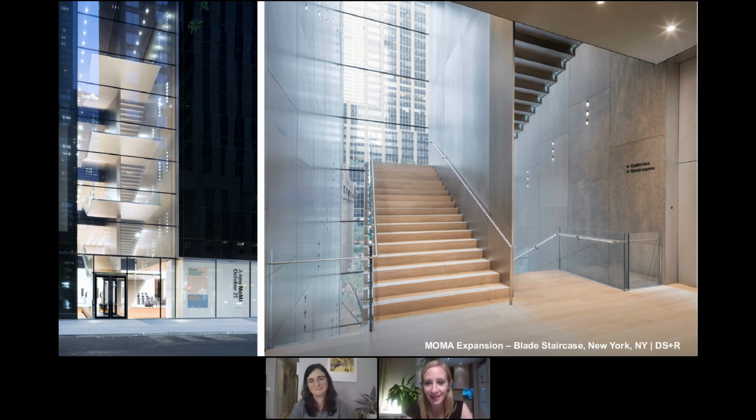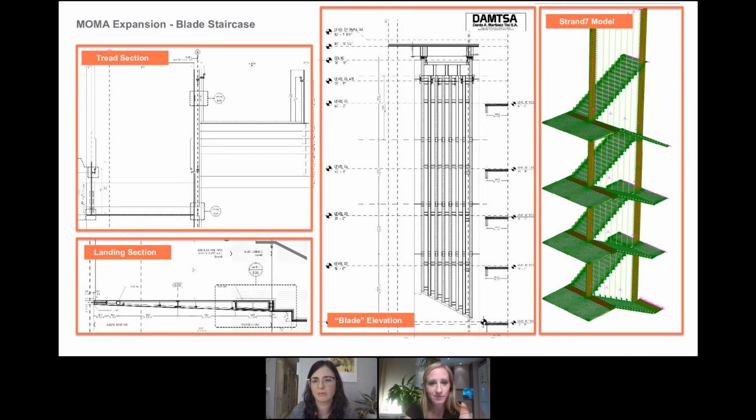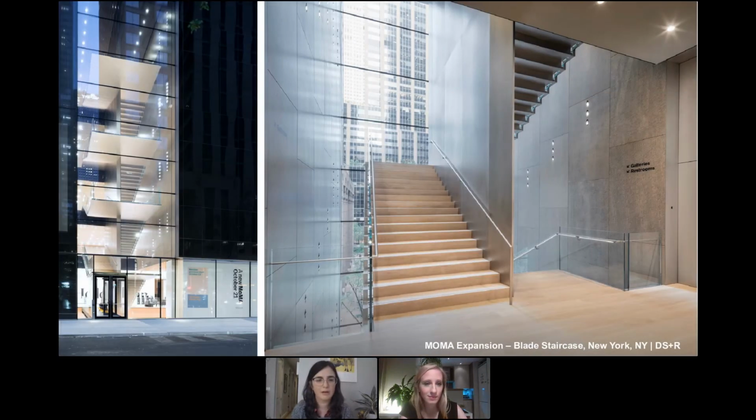So Hubert asked, for the MoMA stair, did this glass stair rail attachment configuration contribute to its overall vibrational performance, positively or negatively? I would say it didn't help. The thing that's not shown in this is that the glass handrail is also considered in our full stair model. It didn't help, but it was not severely detrimental, no. It's just a consideration that we have to take.